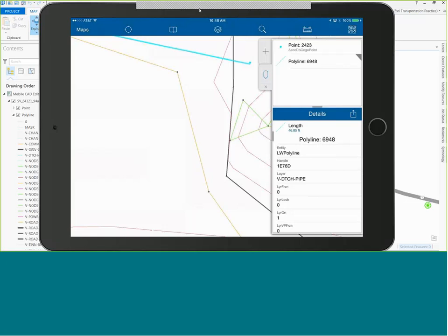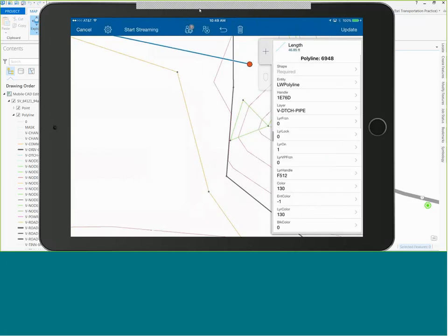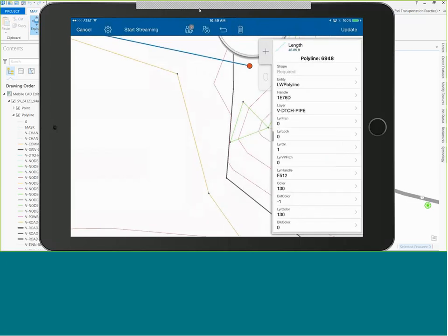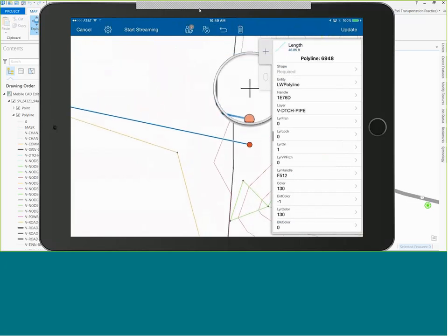Otherwise, right now, if you do want to do editing, you can do it, but you would have to have some geoprocessing on the back end to make sure that this is all post-processed and snapped back together. Then you've got to decide what takes precedence. Is it the node or the line? Long story short, I would recommend that if you're going to do editing, you edit red lines to start until we get to a point where we can reliably do snapping.